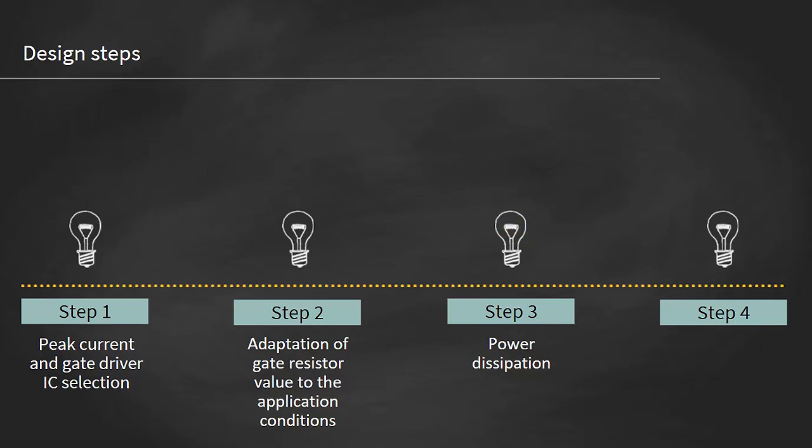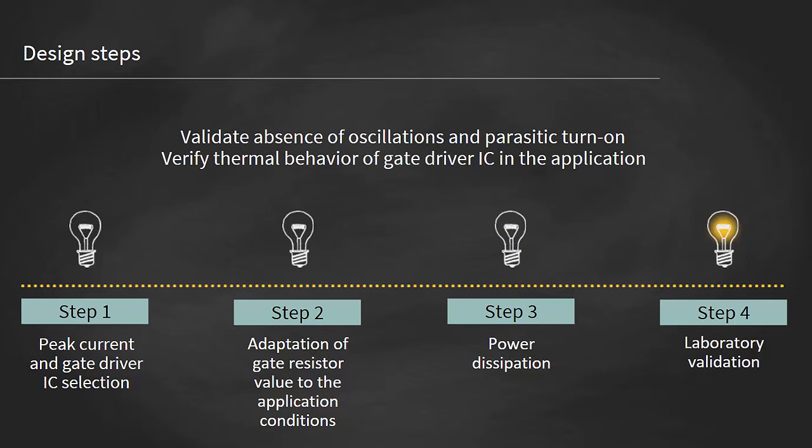The last and most important design step is the validation in the laboratory. This validation provides insights on whether the gate driver circuit is powerful enough to drive the power transistor and whether the power dissipation is within the limits defined in the datasheet.